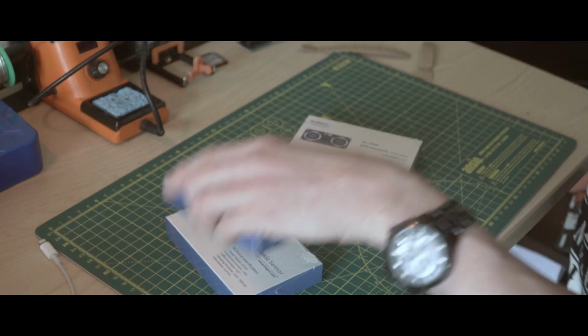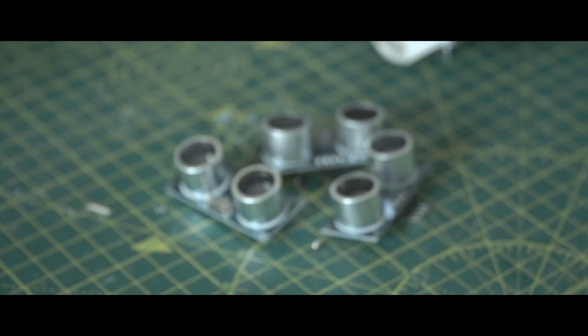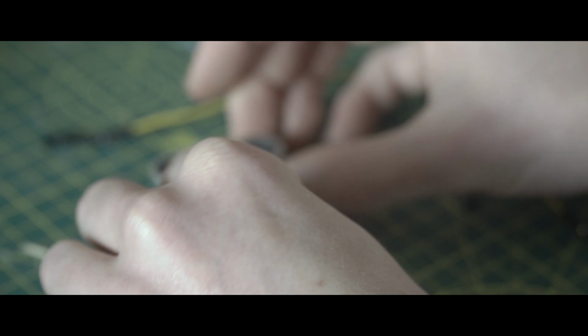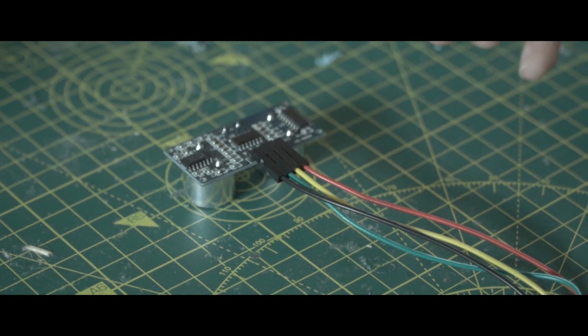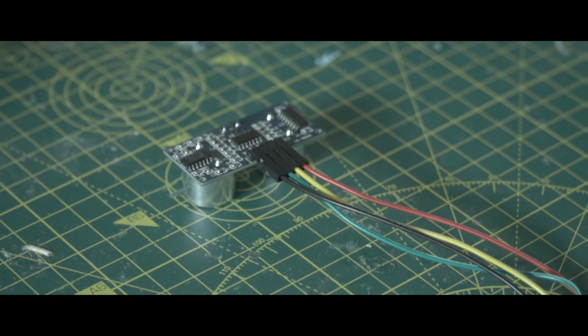Interactivity comes from an array of 3 HC-SR04 ultrasonic ping sensors. These sensors work in much the same way as sonar, so by sending out a high frequency ping, the sensor can listen to the response as it bounces off nearby objects. We can then use the Arduino to measure the amount of time it takes for the ping to return to the sensor. This is known as a time of flight calculation.